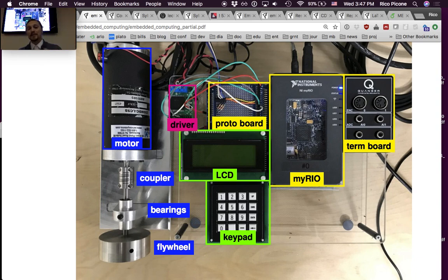Since a motor has coils in it, it has an inductive aspect, not a separate discrete inductor, but part of the windings of the motor. So you can't simply be flowing current through there and flip a switch, or it will probably damage a lot of the circuitry that's driving it, because a large voltage spike will occur.